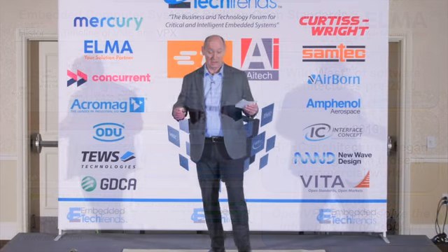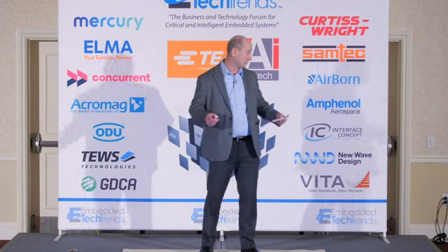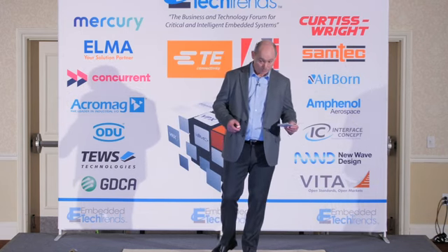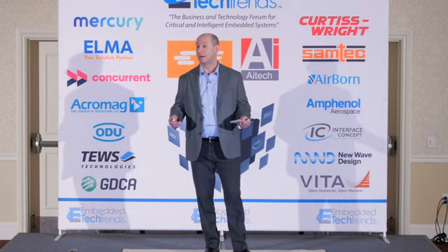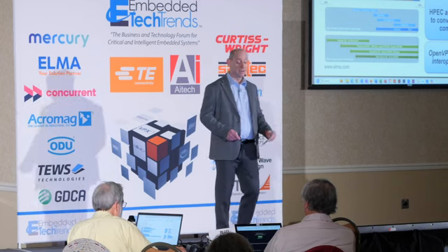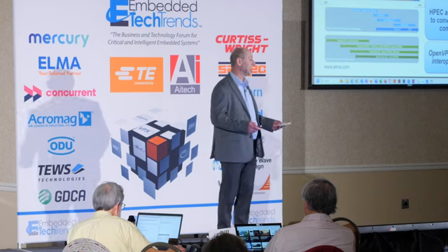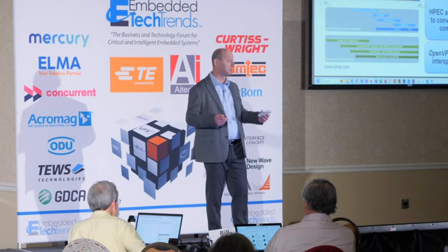VME supported a wide variety of processors, and along with them a wide variety of software solutions, from bare metal to bespoke and proprietary operating systems. It also had a limitation in that it didn't provide the high-speed interconnects needed for distributed computing for processing intensive applications such as synthetic aperture radar and EW and electro-optical and IR processing. So a number of vendors created their own solutions using the P2 connector and high-speed serial switch fabrics, which came along with bespoke software solutions.